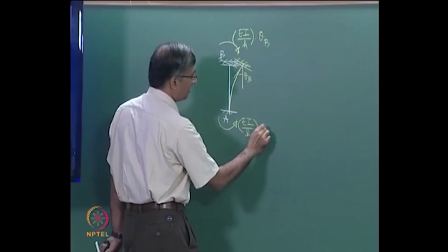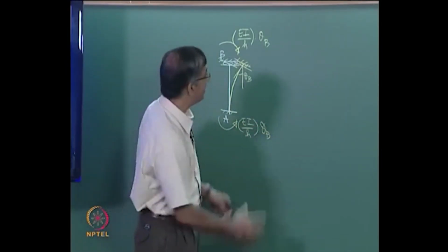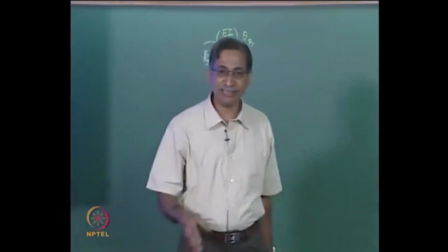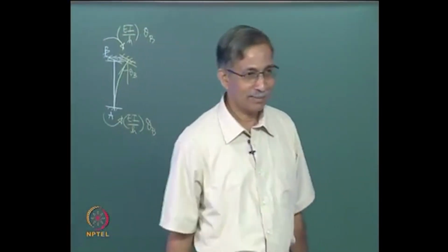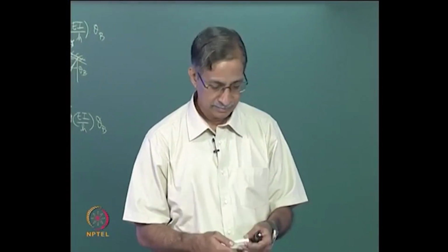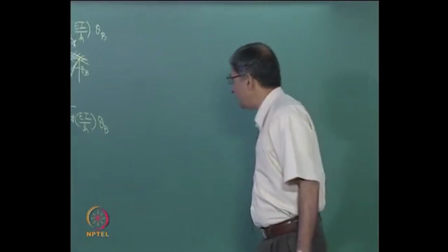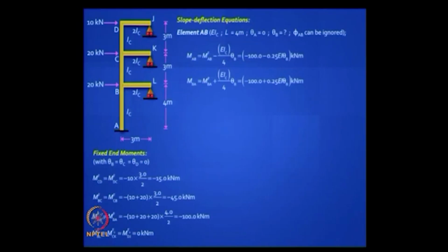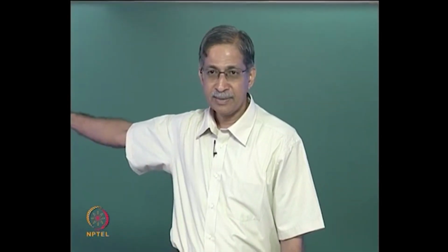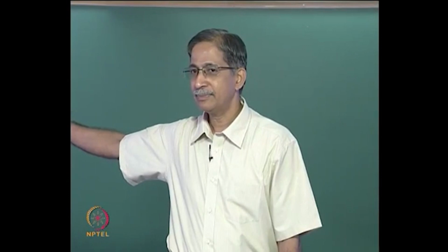So you have done this with the element in the horizontal position in beams. The behavior is exactly the same even if it's vertical. Have you understood? So that's the reason why the formula is MF, the fixed end moment, plus or minus EI theta by L. Where is it plus? At the unknown rotation location. Where is it minus? At the remote end. Is it clear? I think that figure explains everything. Is there any doubt on this? Yeah, please.